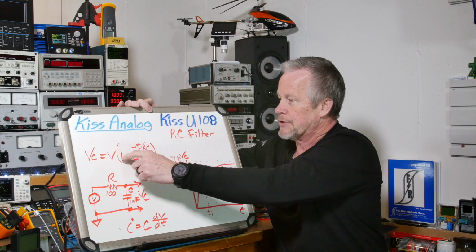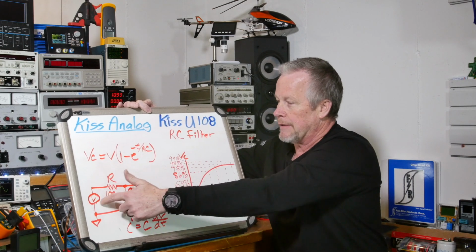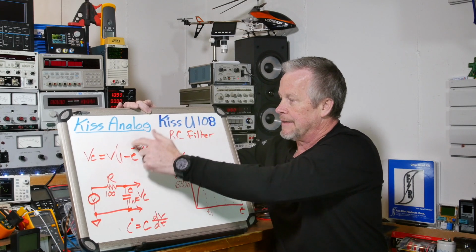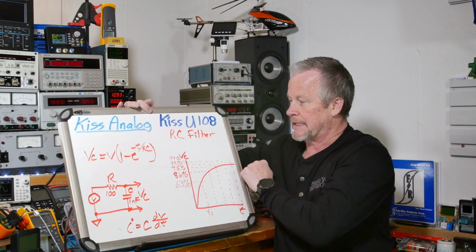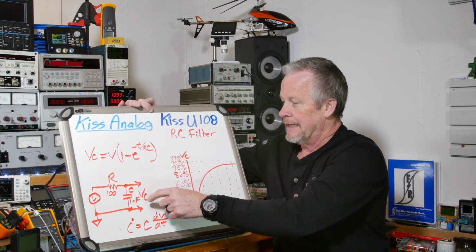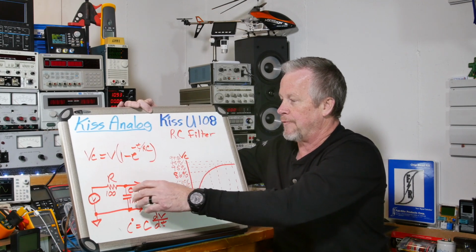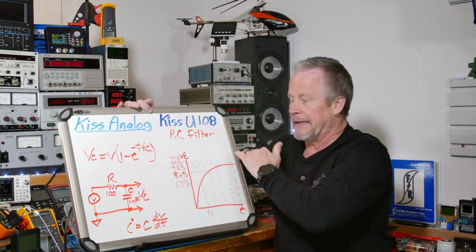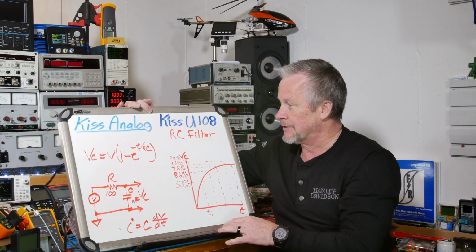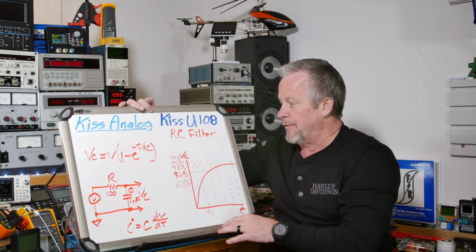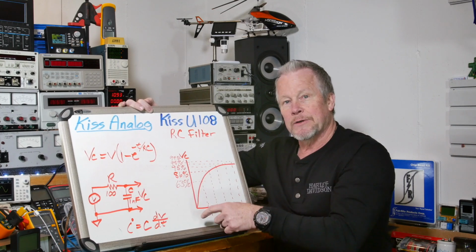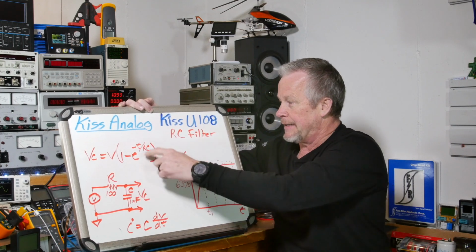So it's voltage times 1, minus this thing, is what this guy looks like. Because as this guy charges up, you're going to subtract that from the voltage. Now if you wanted to plot the current that's going to the capacitor, it'd be just the opposite. It'd be just this term.